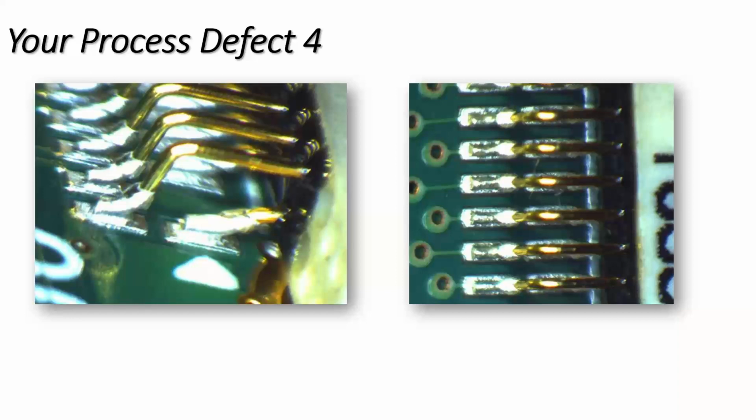I understand that the company is using convection reflow. They're not using nitrogen, because if they were using nitrogen, I would have suggested reducing the nitrogen level, so having a much higher oxygen content. The company concerned uses nickel gold boards. They're using a water-soluble flux. So they've got great solderability. They shouldn't really have a problem with a soldering operation. So nitrogen is a nice to have if they were using it, but they're not.